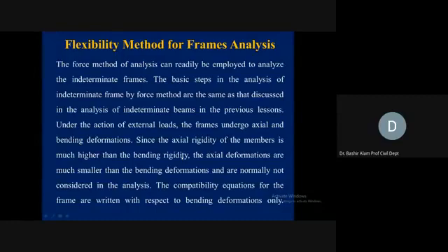The compatibility equations for the frame are written with respect to bending deformations only. So only bending deformations will be involved to write these compatibility equations. Axial will be ignored, and again the reason is those are negligible.